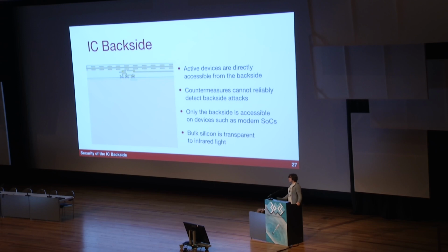How does that make it any easier? But the reality is you don't risk damaging anything if you go through the other side. You can safely thin most chips to something like 10 micrometers or even less without affecting anything on the chip, other than it'll get a little bit more warm potentially, because the substrate's actually really useful for transporting heat away.